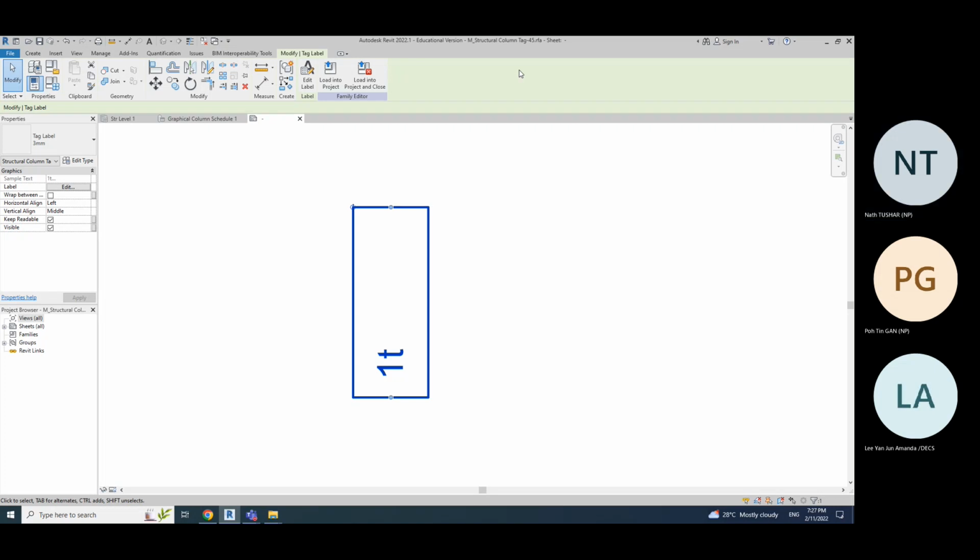.rte. Okay, so there are 3 different file formats used for 3 different purposes. .rte is the template, your base where you start building your model from. Once you create your model and save it, that's .rvt, which you did last week. If you have to make any changes in the BIM object family, you use .rfa.